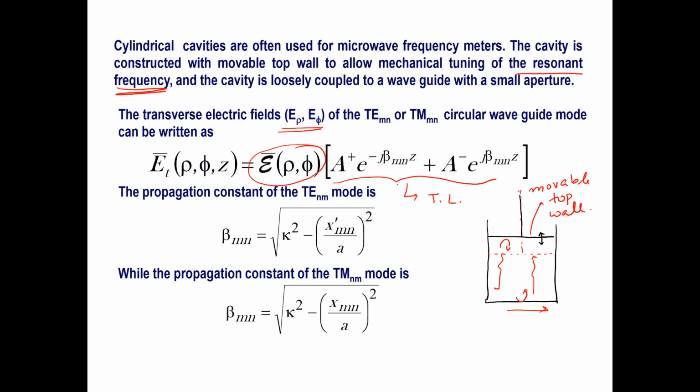Now you can solve it this way exactly, or you can solve it the way we had solved before. You get exactly the same answers. This is exactly what you had done in transmission lines too. So we're not really talking about anything different here. When we were solving the Helmholtz wave equation directly, we were not really talking about anything different from what you had seen in transmission lines before.